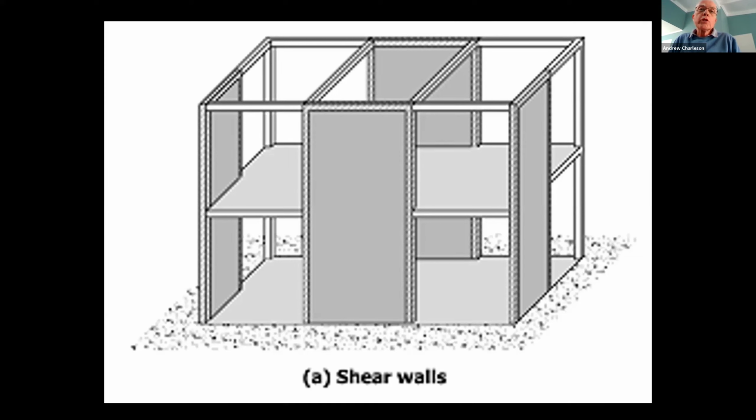And these shear walls must start at the foundation on top of a foundation beam, and they must go directly from there to the roof level. They've got to be continuous up the height of your building. So you've got to find areas in your plan where these walls can pass the entire height of your building.